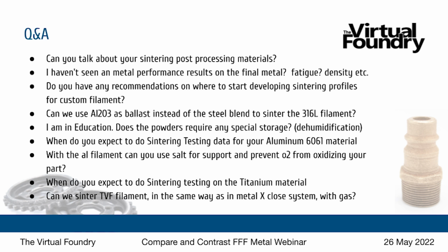So oxygen needs to be managed, one way or another, whether you're using that sintering carbon we talked about or gas. Those closed systems are using gas to manage oxygen. In the Virtual Foundry's open air process, we're using sintering carbon to manage that oxygen.